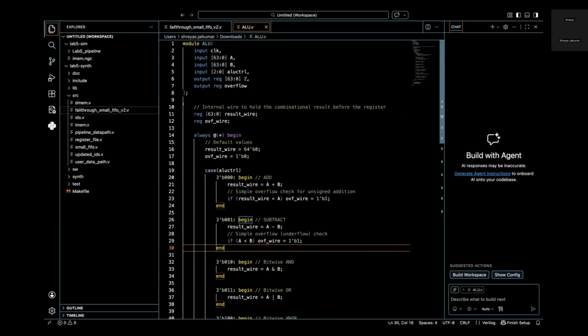So that's it for the ALU. And the second part is building a register file and the memories. It is given that we have to build at least 4 registers, and we went with 64-bit because the recommended, because the NetFPGA data path is also 64-bit wide.